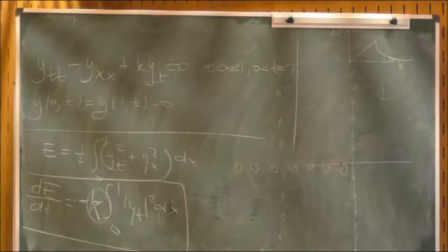This is what this is telling me. It's very delicate to design dampers, because the damper that might increase decay on a number of Fourier frequencies may be deteriorating the decay in others. So making a uniform compromise all along the spectrum is a delicate thing. Okay? Good.